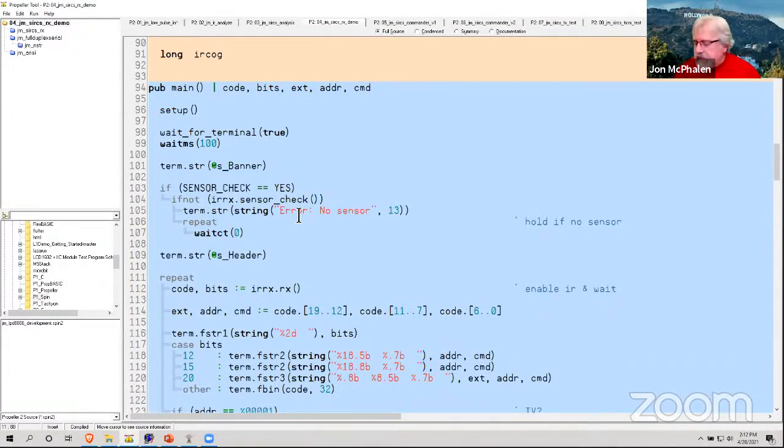And I have that in here. So if you have an application where you want to check, in fact, I'll do it on mine. Where this comes into play is going back to what I told you a while ago about the sensor. Internally, there is a 30K pull-up on the output. So the output when it's idle should be at VCC through a 30K.